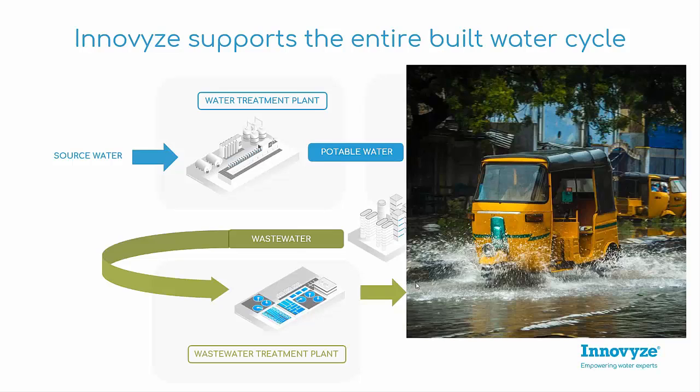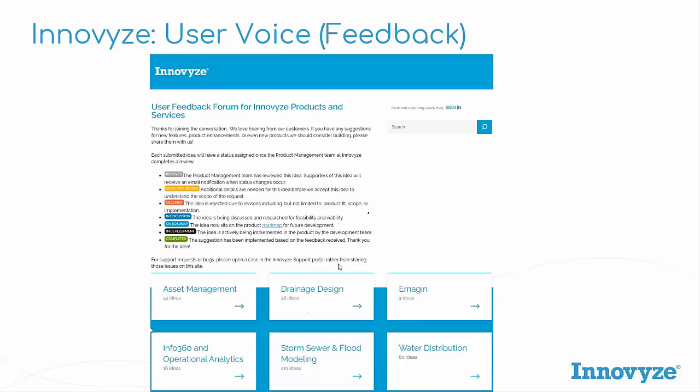With the latest standards, the design and construction guidance that has replaced Sewers for Adoption, and the reviewing of the non-statutory technical standards, it's all leading us into looking at the impact of a development upon the existing catchment and the impact of the existing catchment upon the new development, both pre and post-development. We need to plan out the drainage systems better and understand the consequences of failure better. So that was the reason for sharing that with you.